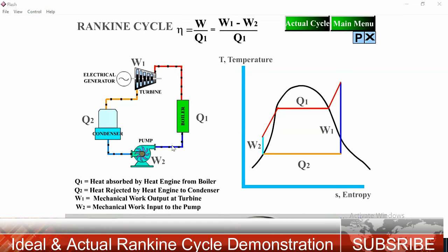You can say the components involved in a steam turbine power plant are the steam turbine, condenser, pump and boiler, and all of these are considered to be control volumes. We will apply the steady state flow process equation on each component.